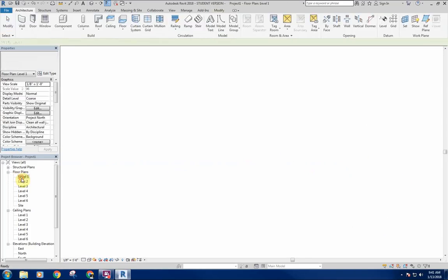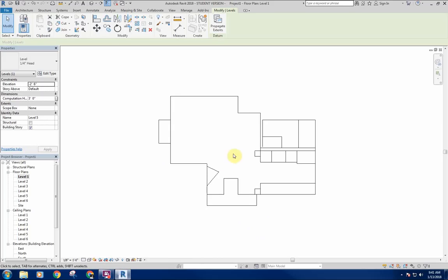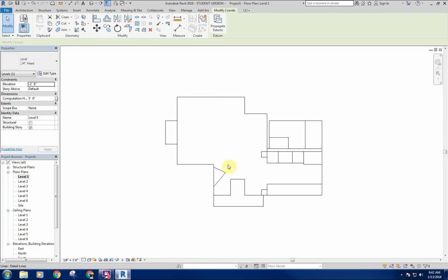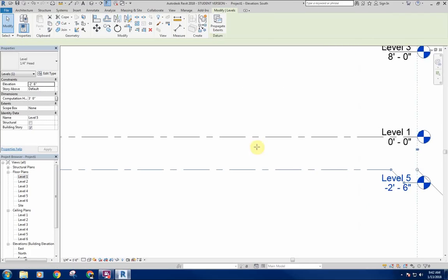This we're going to have some larger spans. We might have some that span this way, but there's not really a good breaking point here. So this might all span this direction, or vice versa. It just depends on how this all ends up laying out. So we'll probably use something like a TJI for that.